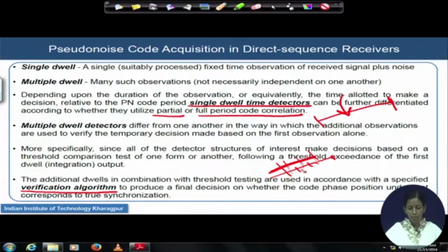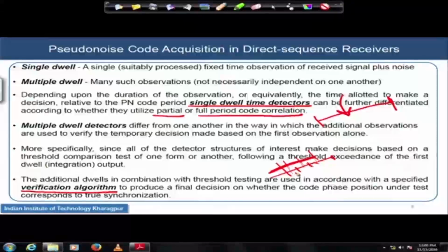One may run the verification algorithm in such a way that there is a search going on for how many times the difference has crossed the threshold value or is below it, and once this search is going on, where to lock. So search and lock, two simultaneous processes, are involved when the verification algorithm is running. You search, and then you lock, devising a logic based on which the locking will declare that synchronization is achieved.